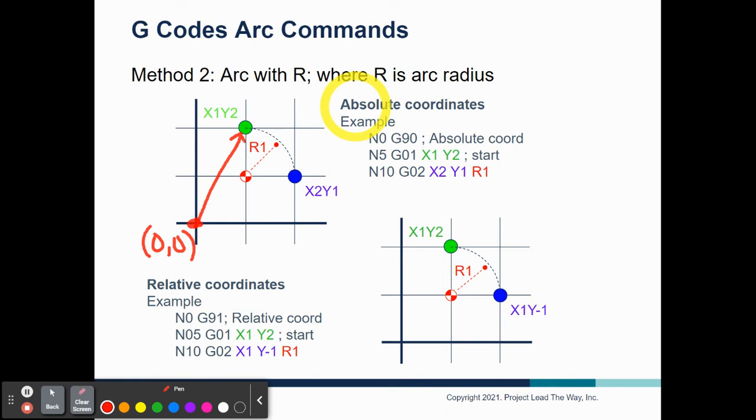Yes, yeah. You can go to the negative. You can go to the negative side. It just all depends, Seth, on where your 0, 0 point is. Because even though I'm saying 0, 0, technically speaking, let's pretend we're milling or trying to create this box, right? I could set my 0, 0 here, which would kind of make sense, I think, as far as the Cartesian plane works, right? But technically, say there's a hole in the middle of this box. Well, our 0, 0 point could also be the center of that hole. So it really can be negative x, it could be negative y, it could be positive x, or it could be positive y. It all depends on what you say your start point is, and that is going to be the power that you guys have as the programmer when you are trying to produce anything.